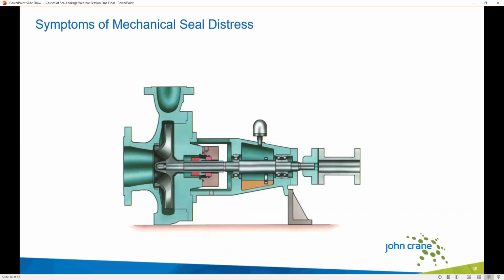So thinking through the process of running into a problem, there's going to be some symptoms. Whether or not we're able to catch those before we really run into an issue is a matter of how big of a problem we're running into, but we'll have a chance initially to observe the equipment externally, which means we're going to be able to use visual indicators, maybe audio indicators. If we have any sort of instrumentation that's taking readings on the pump, all these things can help us address and try to identify problems as they are beginning to occur.